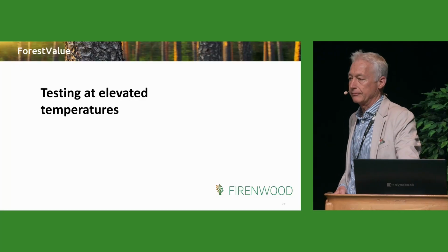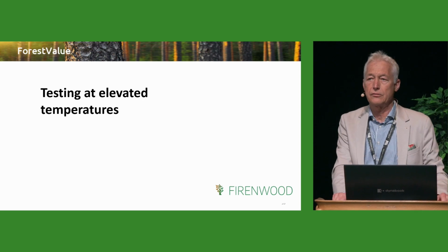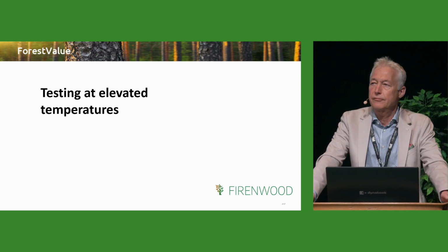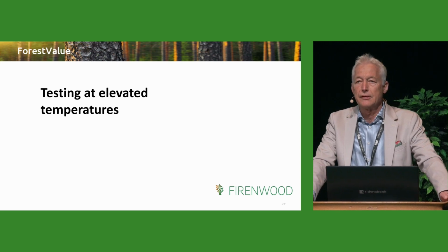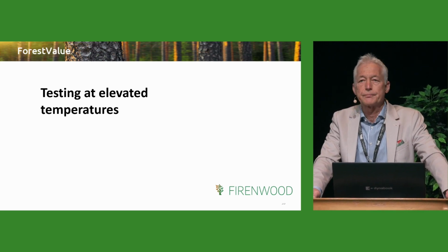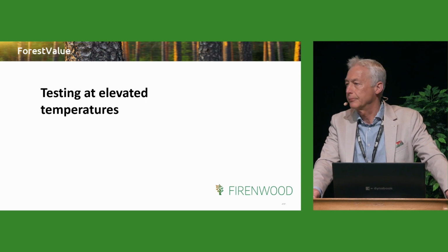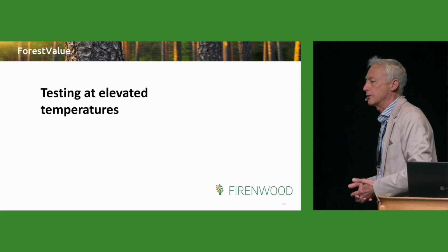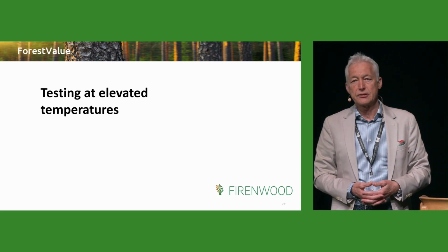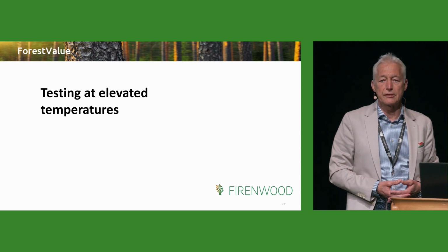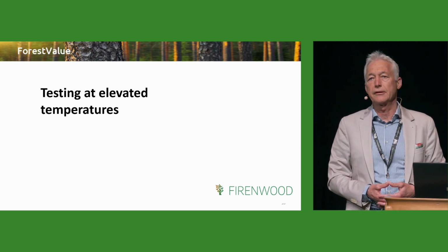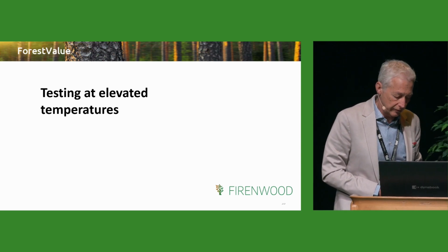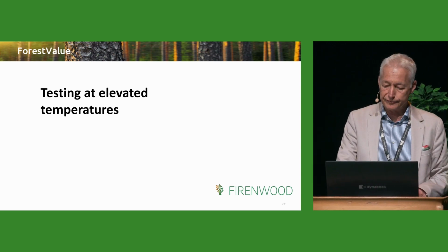You have heard something about large specimens, so-called small specimens, and now you will see some results on tiny specimens. As you may know, adhesive testing today for all structural products is done with small specimens, and the maximum temperature we address today in structural adhesives in Europe is 90 degrees, and for most adhesives only a temperature of 70 degrees is verified, irrespective of what generic adhesive family we have.